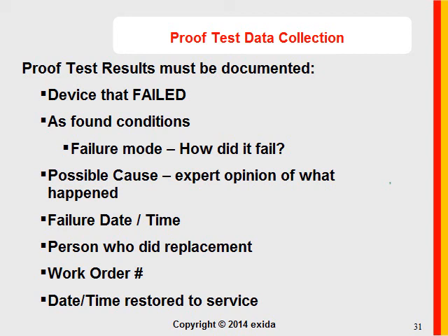When we talk about a proof test, obviously, if a proof test is successful, meaning everything passed, then you want to record that you've executed the proof test, the date that you executed it, and that all steps of that proof test passed.